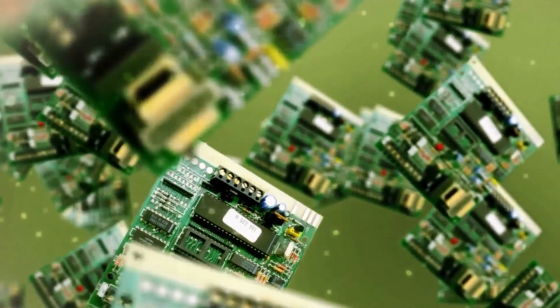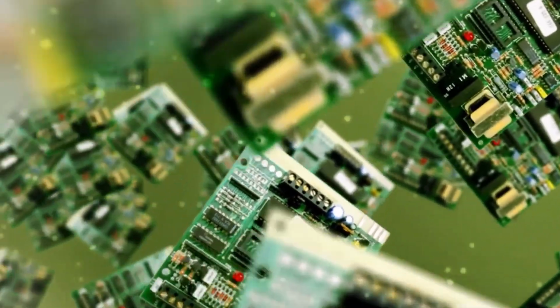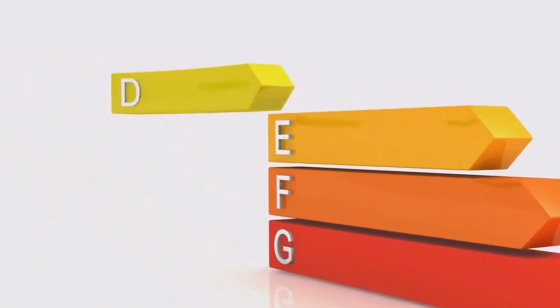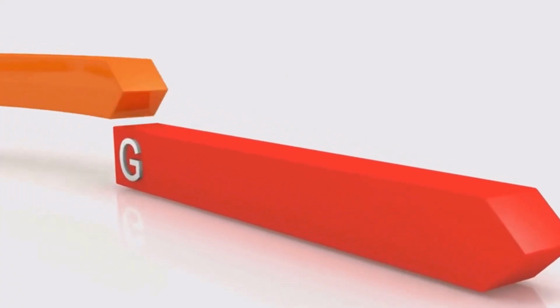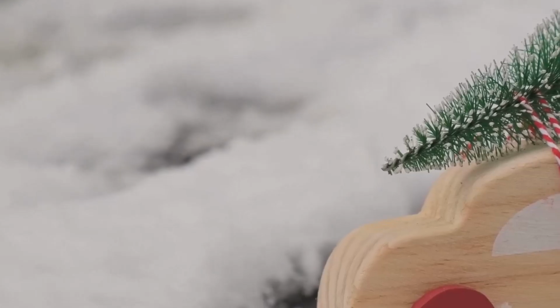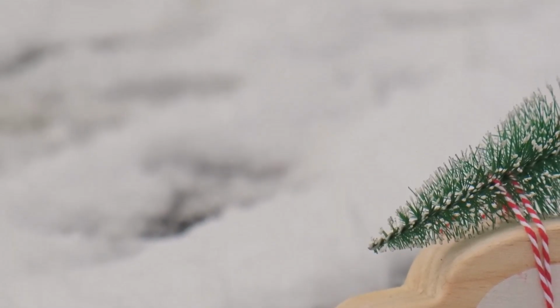This method is very simple to build. It only requires one diode, making it inexpensive and easy to implement in basic circuits. However, its simplicity comes at a cost: inefficiency. Because it throws away half of the AC power cycle, it's not very good at delivering a smooth or powerful stream of DC energy. The resulting DC output is very lumpy or pulsating, which isn't suitable for most sensitive electronic devices. Imagine trying to run a toy car that only gets power half the time. It would move in a very jerky, start and stop motion.